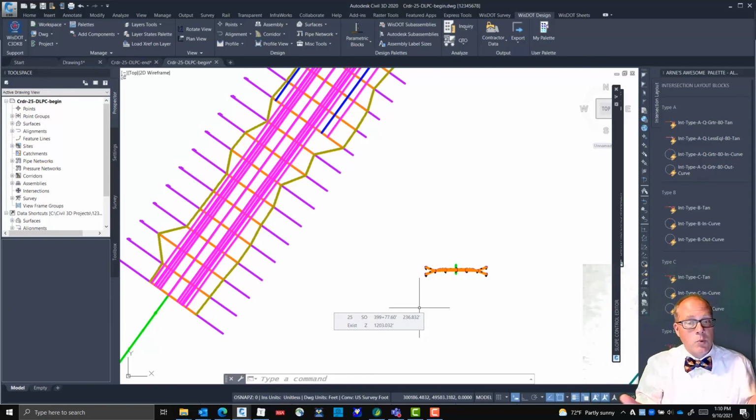If you don't do it this way, you get into managing all kinds of assemblies, all kinds of regions, changing the region limits depending on what's going on, and all of that melts away if you've got a subassembly that can manage all those different links, that you can target those links, that you can control the ditch or fill logic on your own, and get the slopes to do what you want to do.